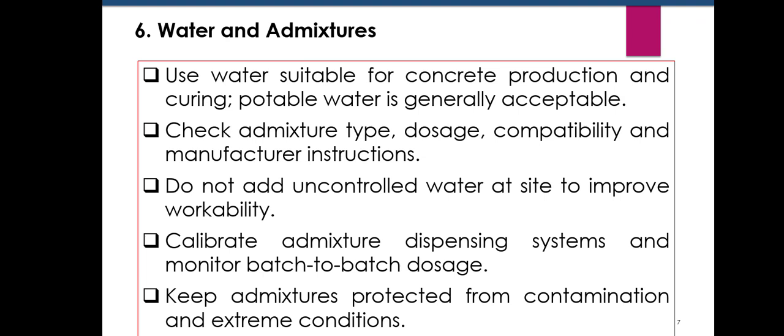So, next is about water and admixtures. Water used for concrete production and curing must be suitable. Normally, potable water is generally acceptable. Admixtures must be selected carefully and their type, dosage, and compatibility with the cement and other materials should be checked.